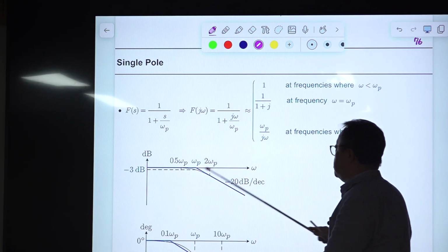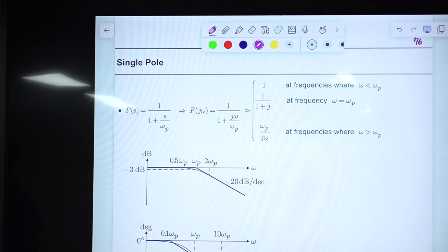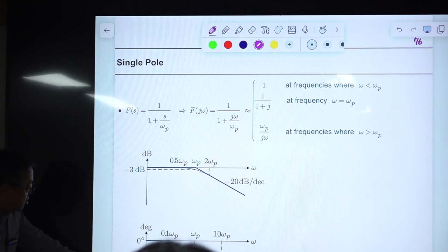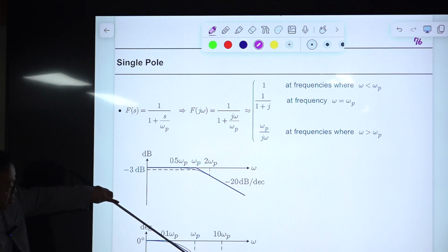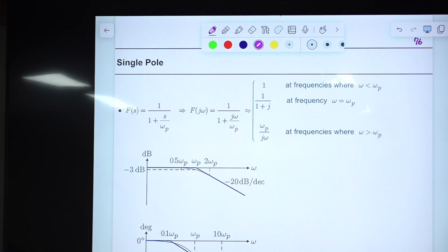The connection of these two asymptotes provides you the asymptotic Bode plot of the frequency response representation of this first order pole. Exact plot as shown here. So we have 3 dB difference as predicted. Okay, and the phase is like this. So phase here is 0 degrees, and here is minus 90 degrees. They decrease linearly. Okay, this is the asymptotic plot. So we have some error. This asymptotic slope is minus 45 degrees per decade. And here we have some error, and we know this error.